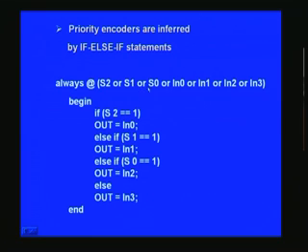So the next thing we are going to see, once again already covered, is a priority encoder as such, and this is the always block which brings out the priority encoder. First, this is given the topmost priority. For example, there are 3 selects, you can regard it as a single 3-bit input, or rather as 3 different inputs. S stands for the select. So we have 3 selects here, and we have 4 inputs once again. It's also a mux basically, and you need to get either in 0 or in 1 and so on, depending upon S2, S1 or S0 in this fashion.